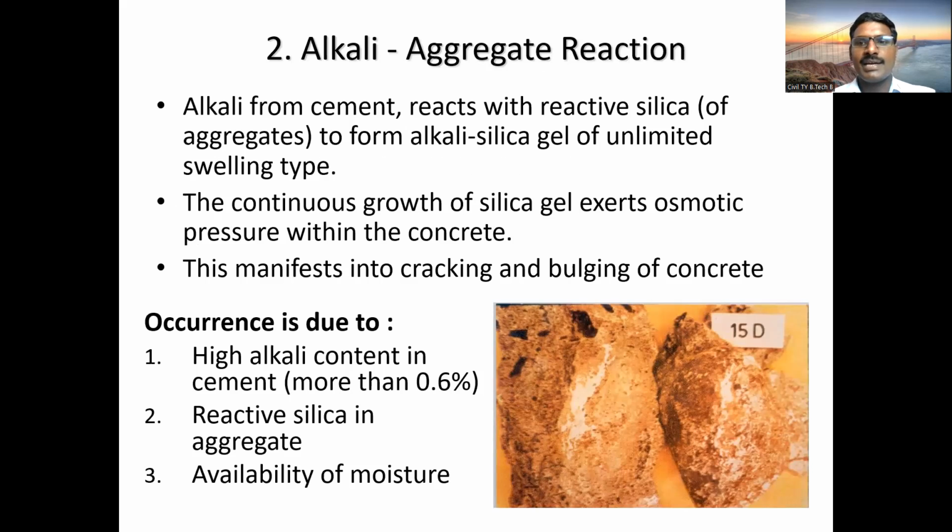So then the alkali aggregate reactions. Have you seen sometimes the concrete will show such color? I think you have seen many. Such images you can see near the toilet area where the toilet water is on the concrete surface. There you have seen this alkali aggregate reaction. So the alkali from cement reacts with the silica to form alkali silica gel of the unlimited swelling type.